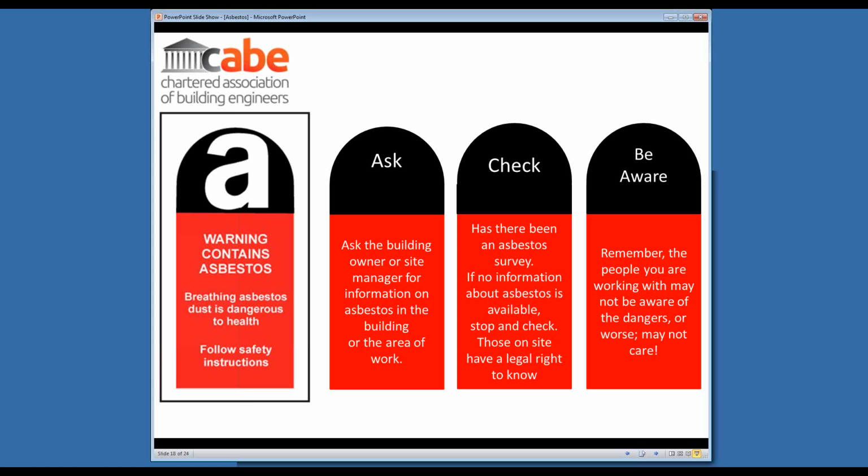That's the basis of our asbestos register. And if you are in charge of a commercial premises, you may simply find that contractors, before they're called to site, particularly heating engineers, may ask for a copy of that, so that they know whether the flues and things they're likely to encounter are likely to cause the employee who's doing the maintenance or the service of the boiler an issue.